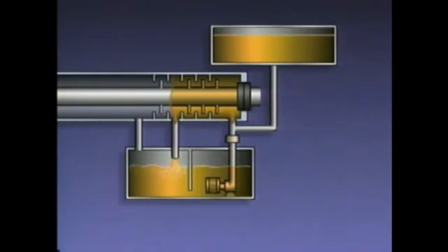As the oil comes in contact with the gas in the compressor, some of the gas is entrained in or carried along with the oil. The gas separates from the oil in one of the compartments of the oil reservoir. The gas rises up through the oil and returns to the compressor through a gas return line.